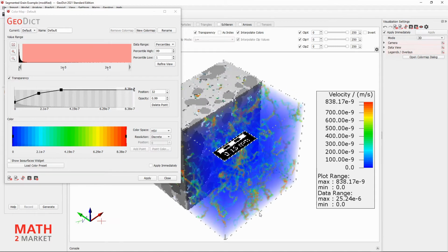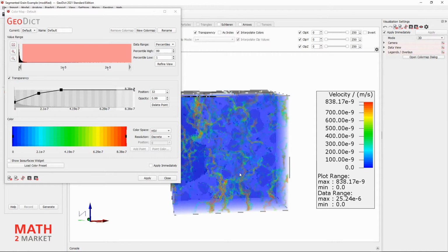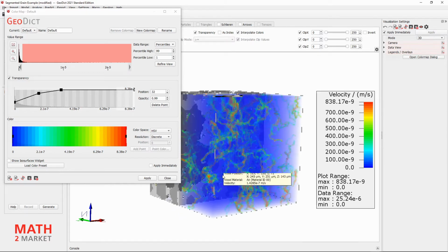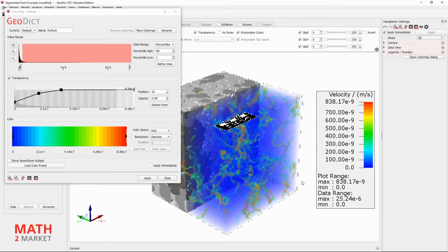The reason for this is the light absorption when the transparency of the volume field is switched on. The deeper a pore tunnel is located in the volume field, the bluer it is colored by the values in front of it. We encounter this effect almost daily when we look at distant objects. Due to the ozone in our atmosphere, distant objects are colored bluish. We can make use of this familiar effect here to help the viewer with the depth perception of the data.